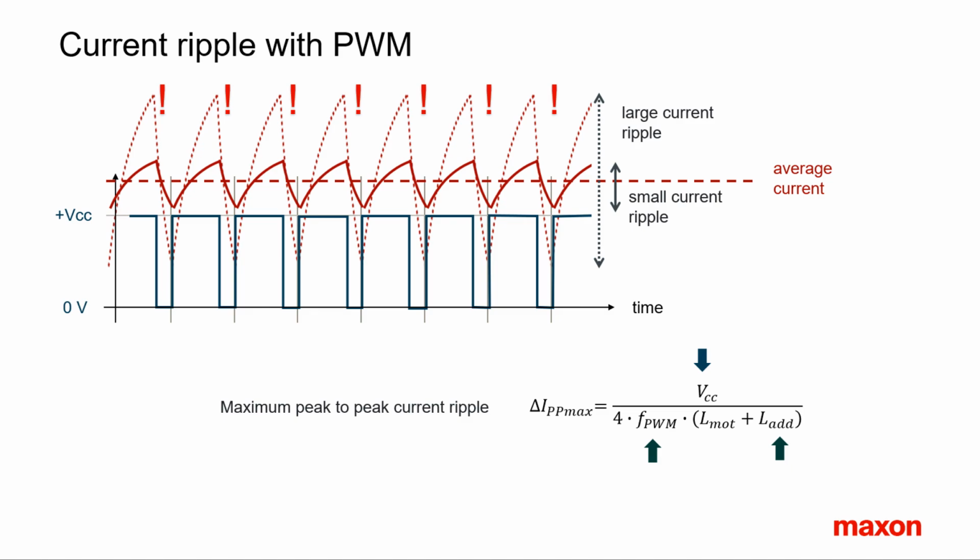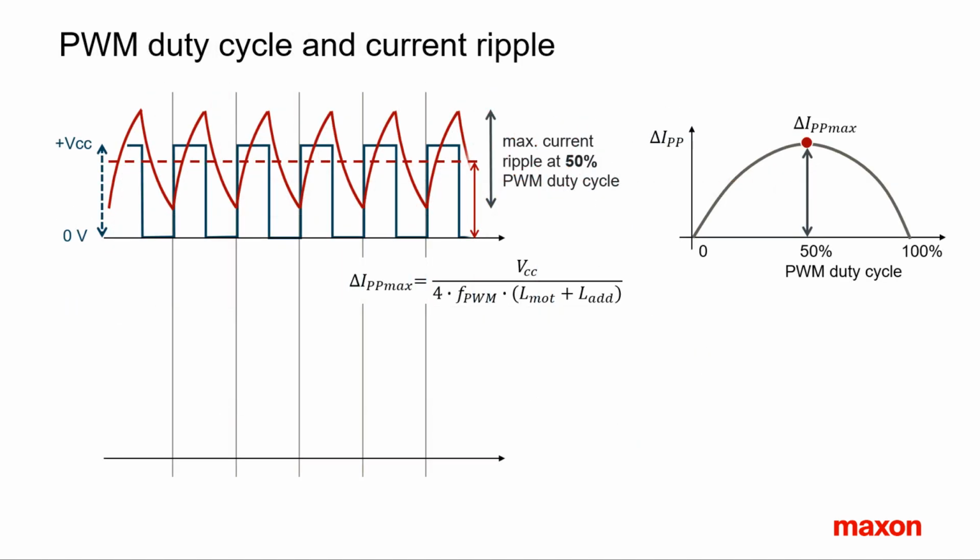Be careful. Motor inductances depend on frequency, and for typical PWM frequencies, they are about 3 times smaller than the catalog value specified. Observe, this formula is valid for the worst case, when the required voltage is just half the supply voltage, corresponding to 50% PWM duty cycle.